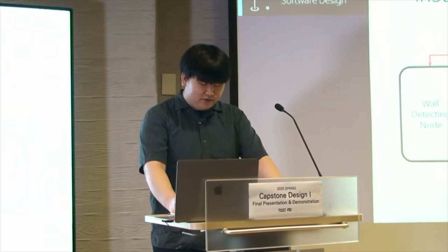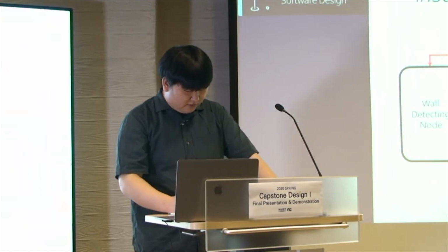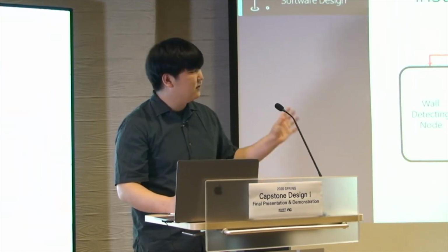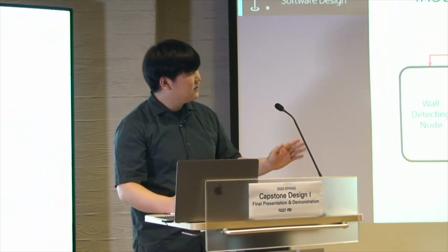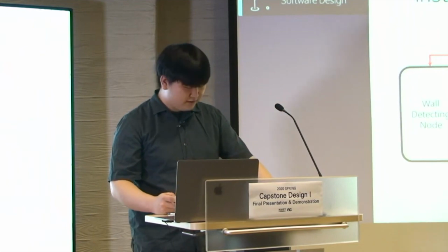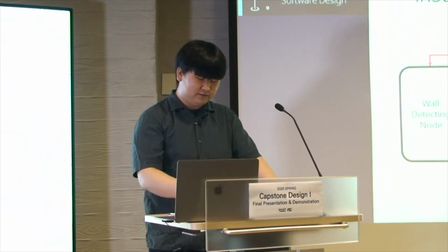Our original plan to get through the entrance zone was line following, but we realized that this method is extremely unreliable when the vehicle is on the bump, since the vehicle continues pitching up and down. Instead, we made a world detecting node which controls the vehicle using LiDAR information.